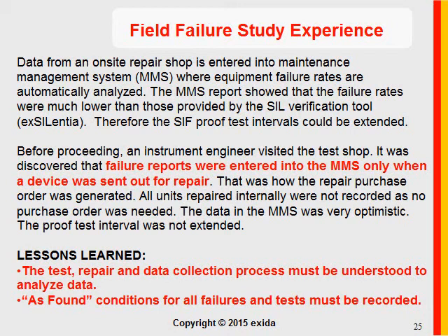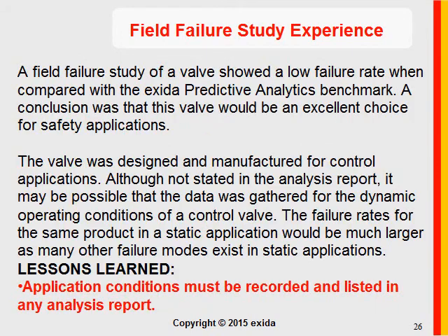All units internally repaired were not recorded as a failure because they didn't need a purchase order. Oh my goodness, it's no wonder the data was extremely low. The proof test interval was not extended. The test, repair, and data collection process must be understood, and as found conditions must be recorded.